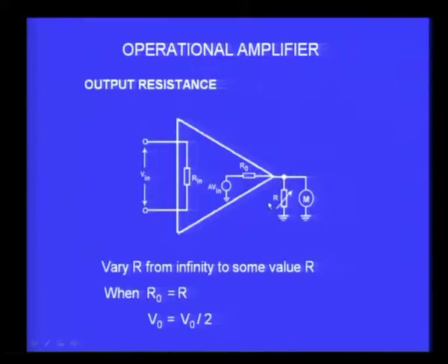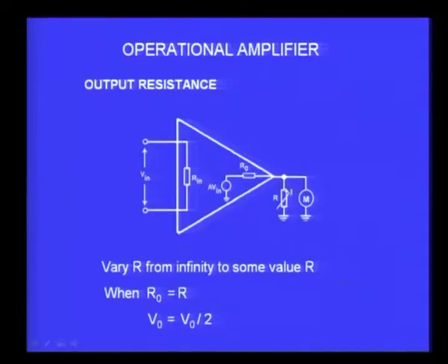Here you should also remember, I should caution this, I have assumed this voltmeter which measures the output voltage has infinite resistance or very large resistance compared to the resistances in the circuit. In this case, the output resistance in general will be a very small value. I already mentioned that in the table the typical value for 741 is 75 ohms.